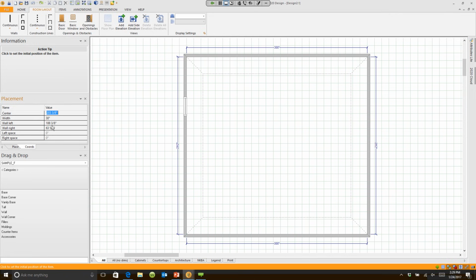Write this down. I've said this a couple times. Write down 3 letters. T like Tommy, A like Apple, B like Bobby. T-A-B, tab. That's the key on the far left-hand side of your keyboard. If you let go of your mouse and you hit the tab key, every time you click it, it scrolls through your counters. So I could go down here and say width, 42 inches.